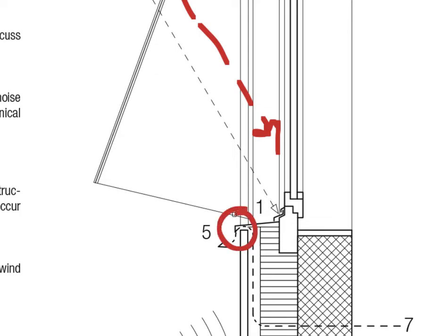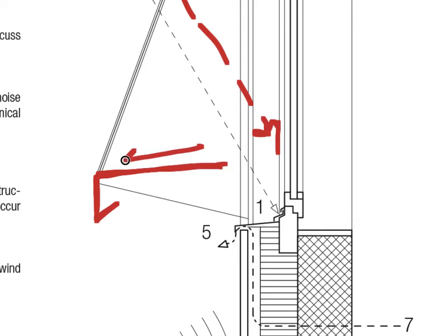With the windowsills, here we can see more like a metal sheet that's bent into place, and if we zoom out a little bit or have a closer look at it, one of the most important things is that it's actually laid to fall. So there's a tiny little bit of a slope, making sure that the water is actually flowing away from the window and it's not sitting in here and potentially starting to seep in.